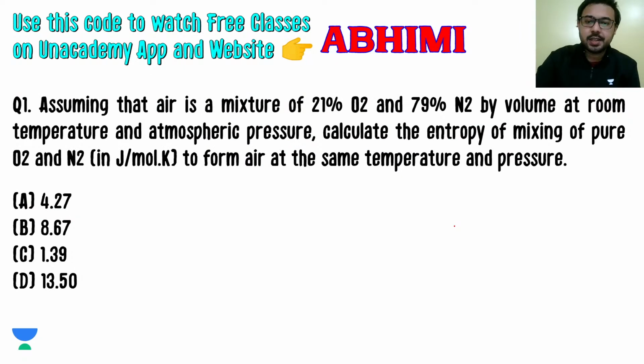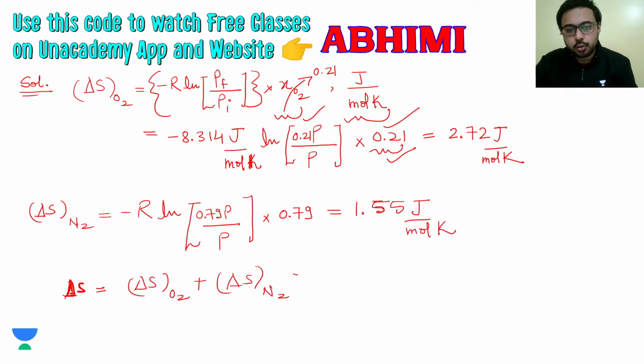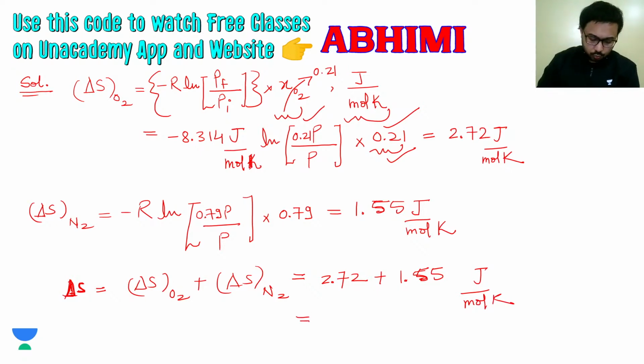So what is the change in entropy of mixing this pure oxygen and nitrogen to form air? So the change in entropy that we have to provide as the answer is going to equal delta S for this oxygen plus delta S for this nitrogen. So this will be 2.72 plus 1.55, and the units are the same for these individual values.